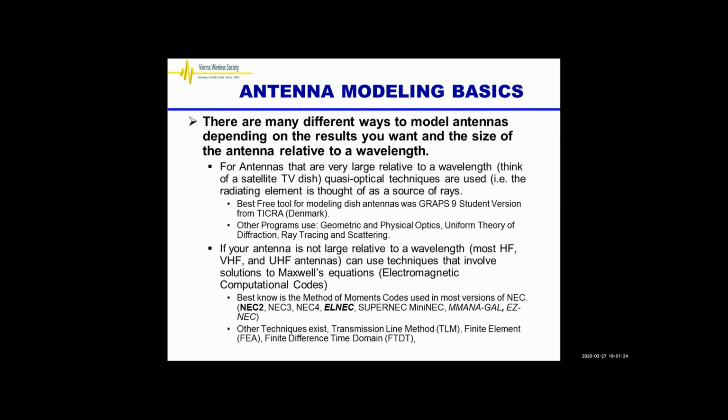Then MMANA-GAL is very popular in Europe and is actually a rewritten version of MiniNEC. And there's also EZNEC, which you may have a copy of if you have an ARRL antenna book, because they included it on the CD. There are other techniques: transmission line methods, finite element, finite difference time domain, but we're not going to go there.